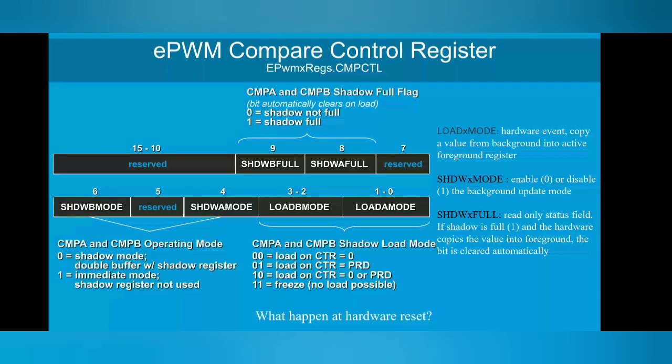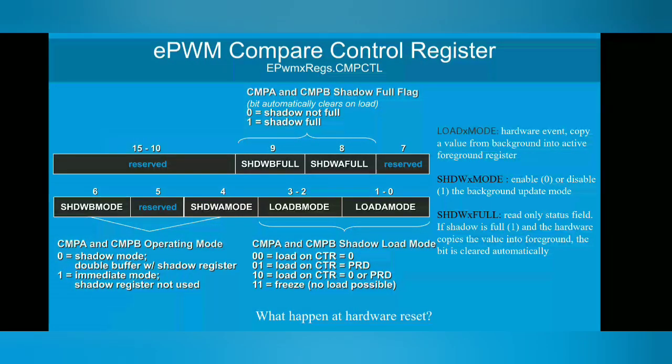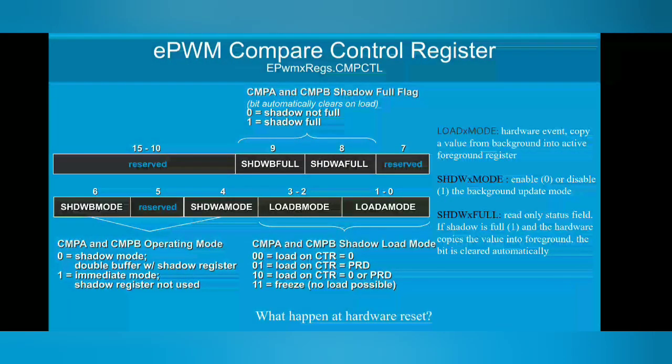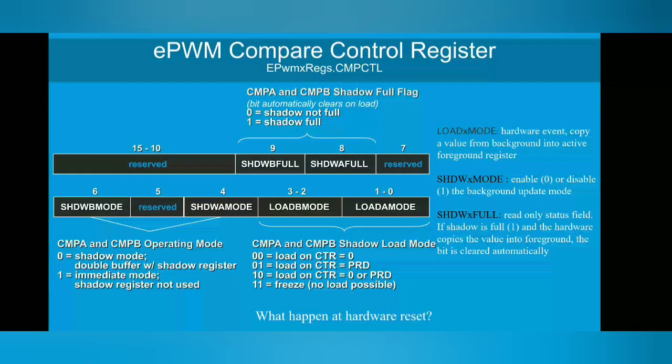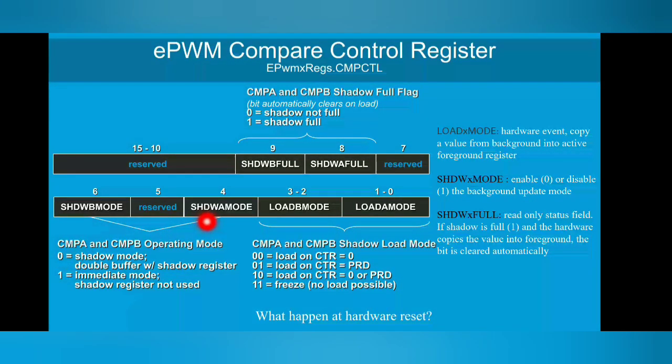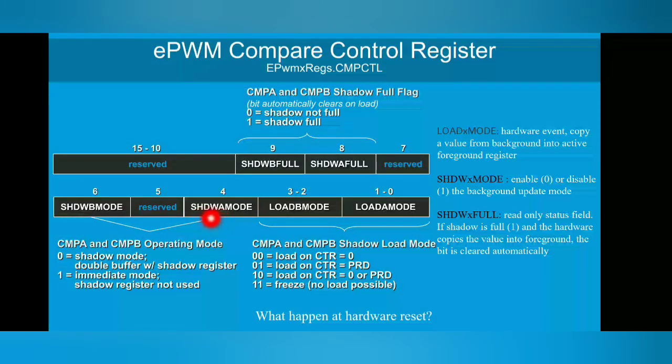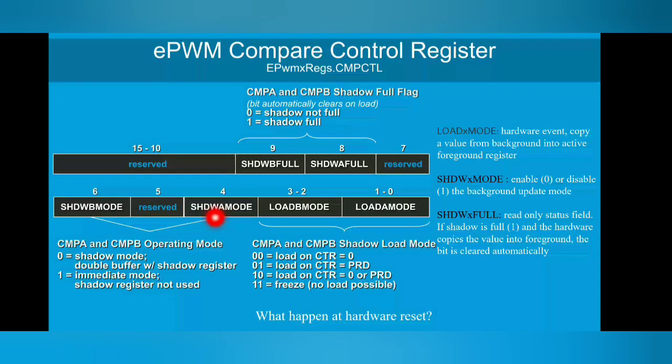Now the thing is, by default, when your DSP processor resets, the shadow registers will always be enabled. This is an important feature for the compare registers. So it will always be enabled. We don't need to use it, we don't need to enable it again.